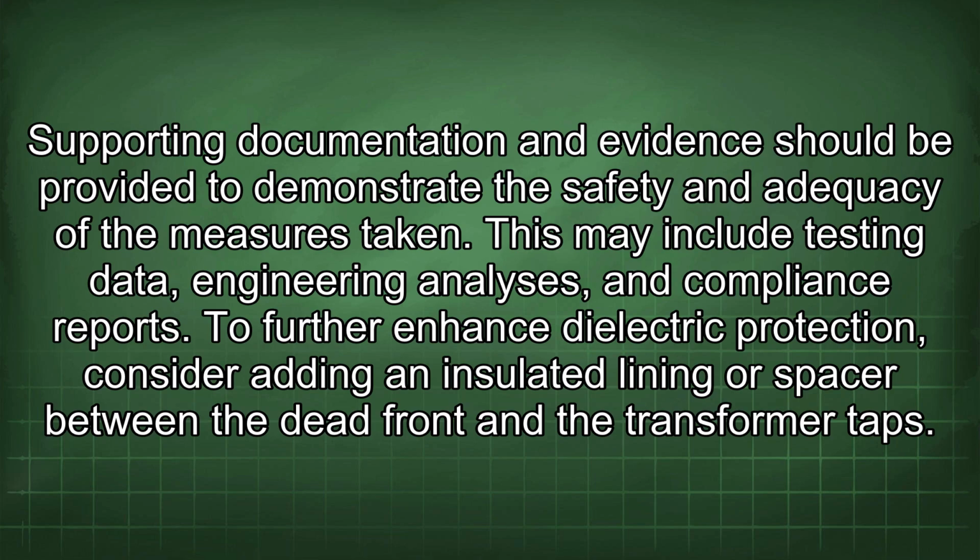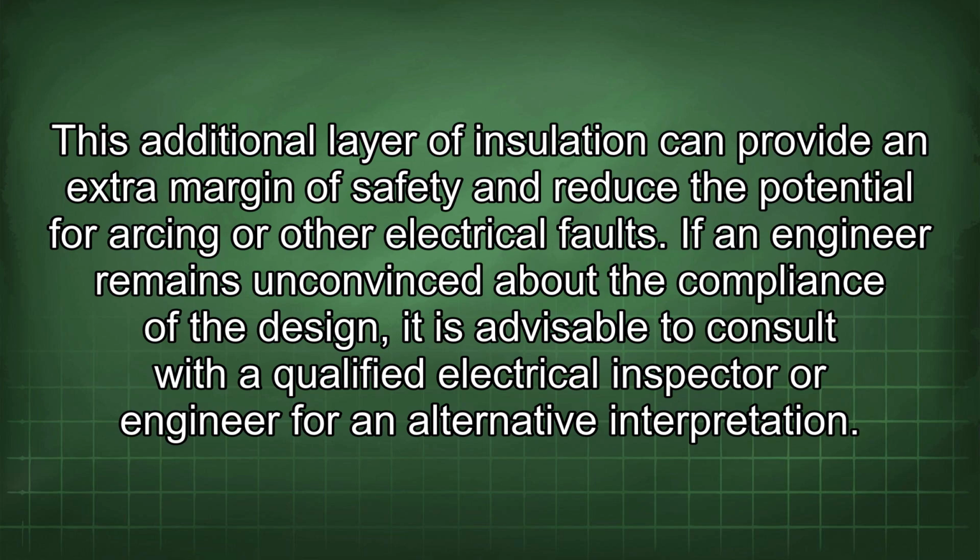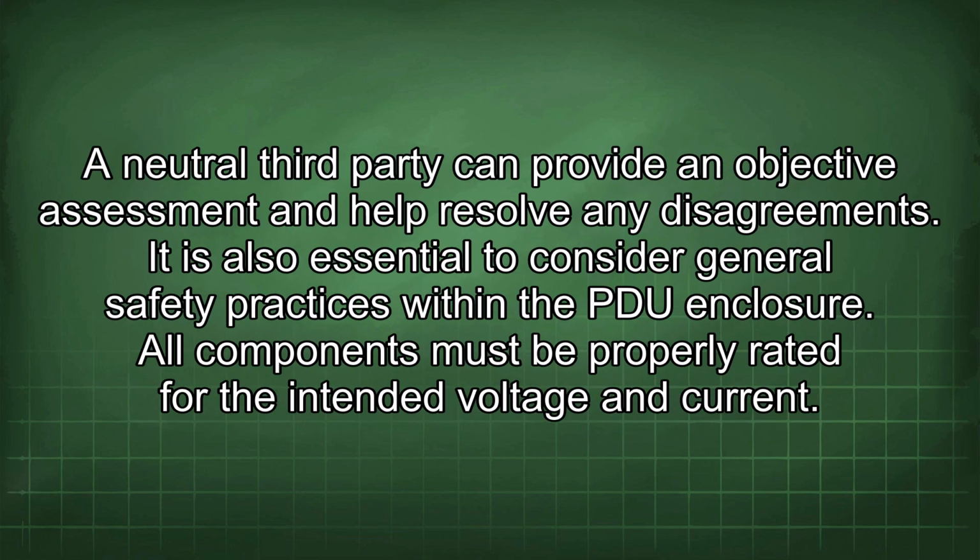To further enhance dielectric protection, consider adding an insulated lining or spacer between the dead front and the transformer taps. This additional layer of insulation can provide an extra margin of safety and reduce the potential for arcing or other electrical faults. If an engineer remains unconvinced about the compliance of the design, it is advisable to consult with a qualified electrical inspector or engineer for an alternative interpretation. A neutral third party can provide an objective assessment and help resolve any disagreements.